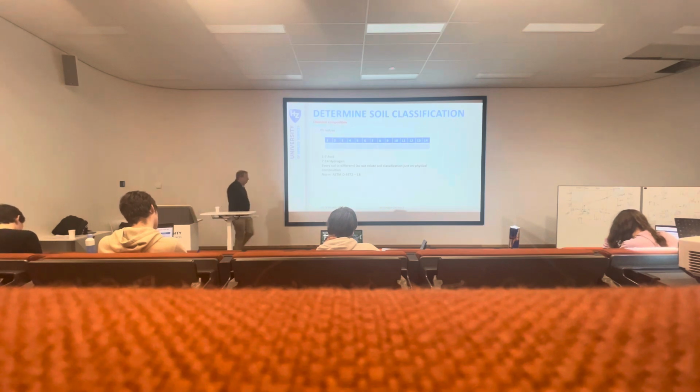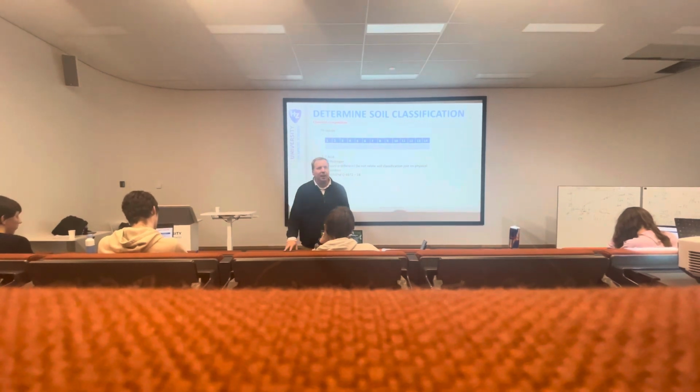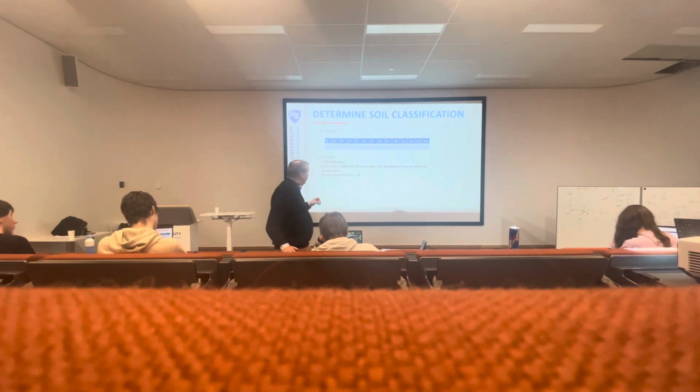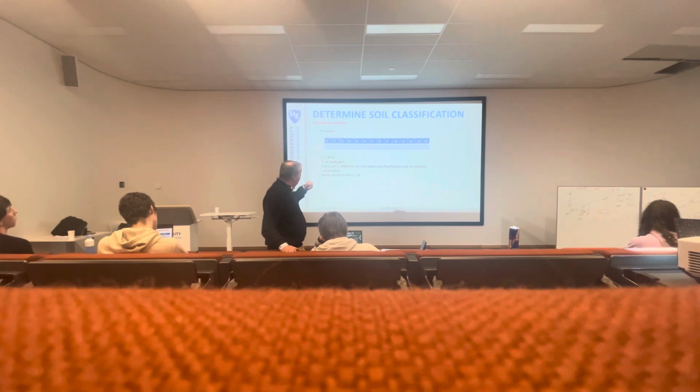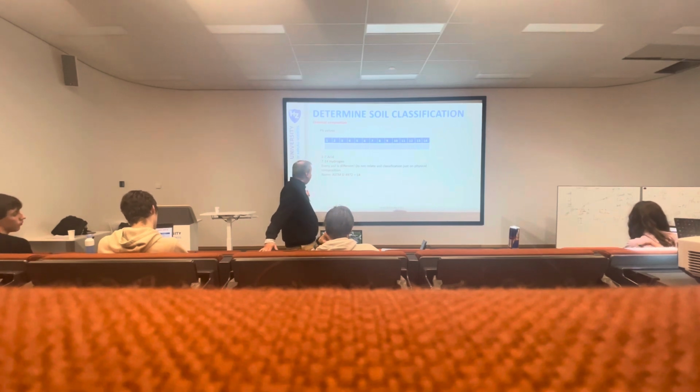Acidity. So pH neutral is 7. When it's less, we are in an acid environment. When it's more, it's a basic environment. Cement works best with pH values of 8, 9, 10. Cement itself has a pH of 12, even 13. Keep in mind you can also get burned with a high pH level. It's not only with acidity.